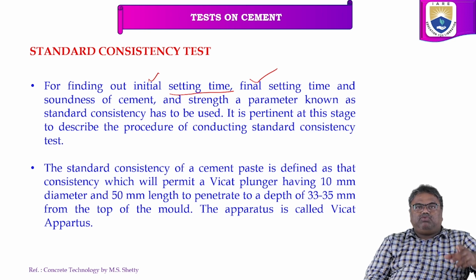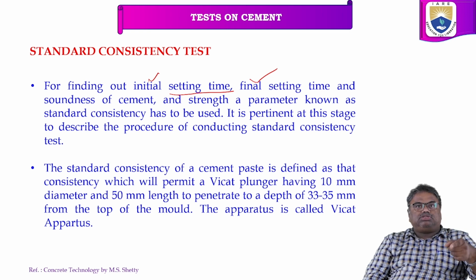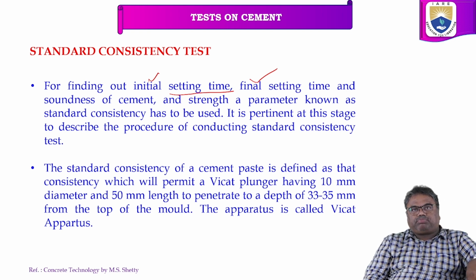Especially, we will find the water cement ratio. For the consistency of water cement, we can find out the water cement ratio by using this standard consistency test, right?